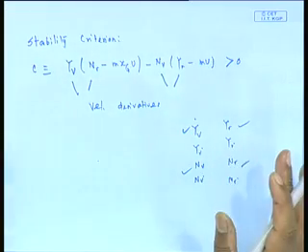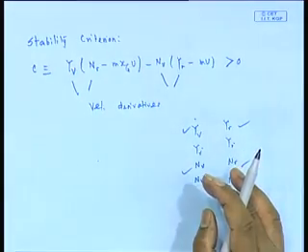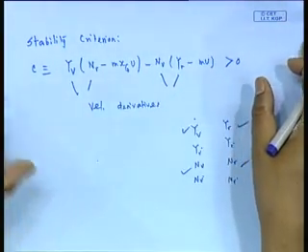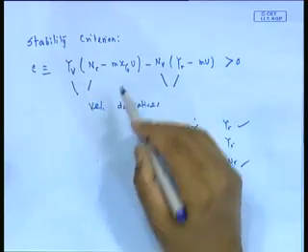is a measure of stability, and we find that the measure of stability is fully connected to the hydrodynamic derivatives. You cannot say I will not study hydrodynamics in order to find out whether the hull is stable or not, because stability is primarily decided by the interplay of the hull forces created.